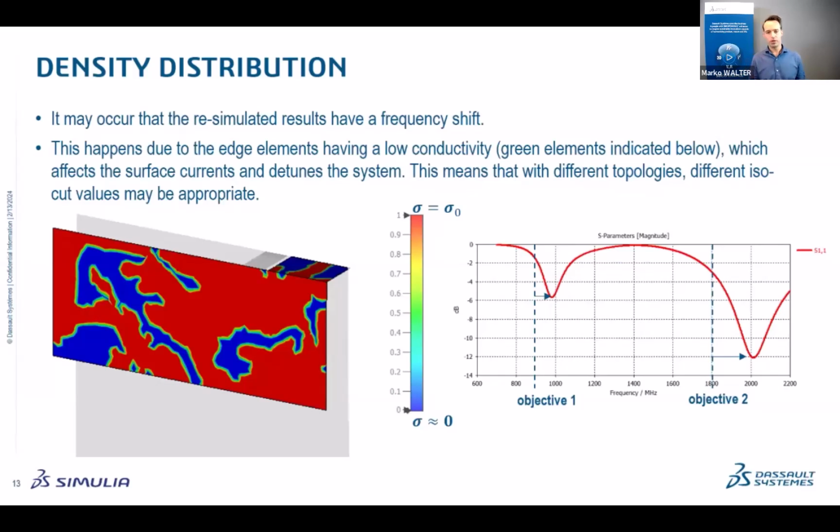And the reason for that is that we are actually working with intermediate densities, which can be observed here from the connectivity, basically going, if you look at the color ramp there, from close to 0, which is essentially my vacuum or my air, to a very high value for a good conductor. In this case, I think it was copper or something. The result is that everything in between is essentially posing dissipated losses to the signals, right?